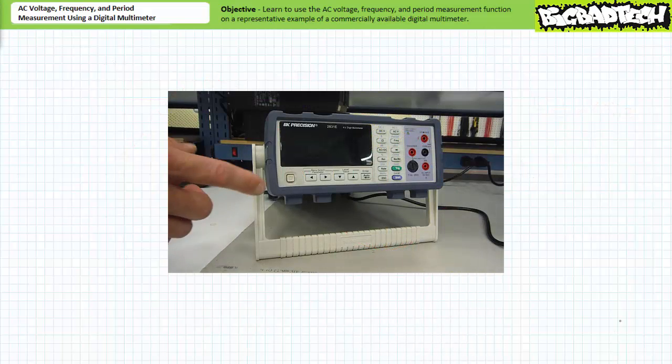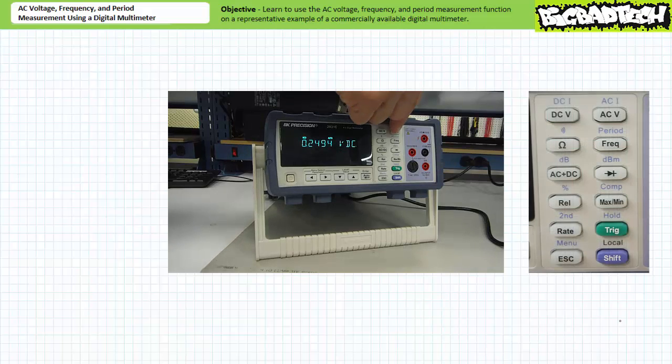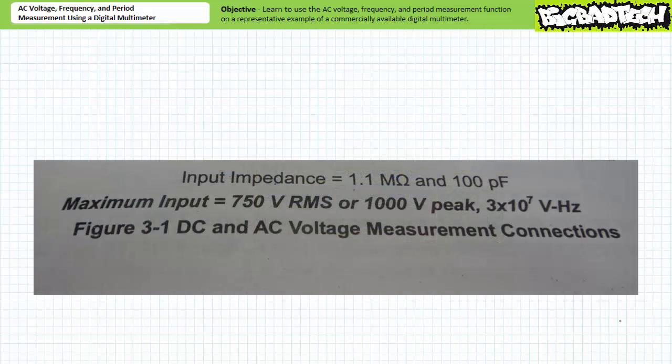Upon powering up the BK Precision 2831E, we see it does a quick functions check and immediately defaults to the DC voltmeter function. Place the DMM in AC voltmeter mode by pressing the AC voltage function button on the upper right-hand side. The manual for the BK Precision 2831E shows this particular DMM is limited to measurements of voltages below 1000 volts peak or 750 volts RMS. The voltage range we intend to measure is well below these upper limits.